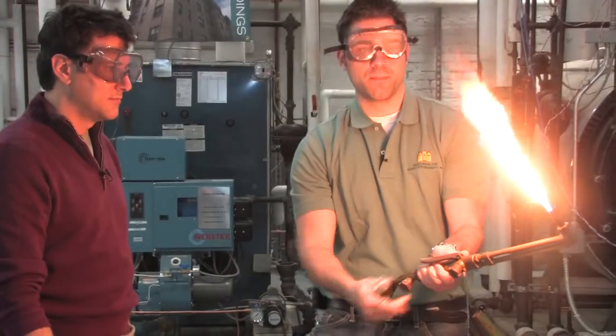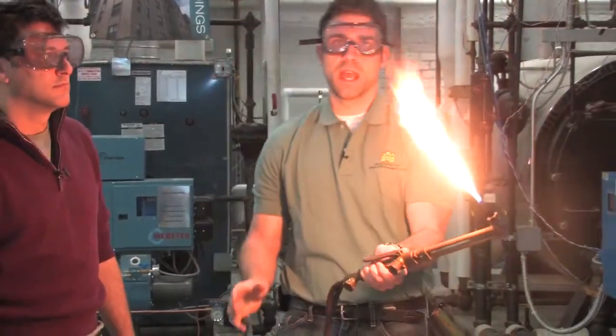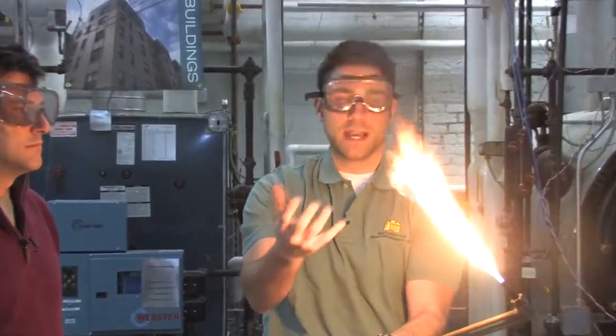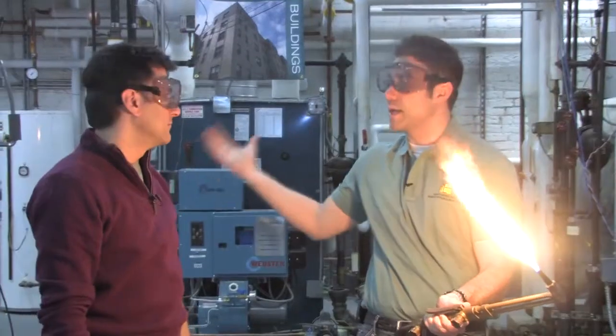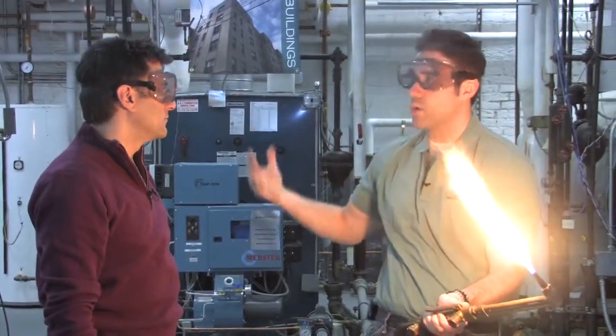So you see the flame. It's a real orange flame. And if you look at the top, you see a lot of the black soot that's forming up here. Yep. Because we're not getting enough ambient oxygen inside this flame to be able to burn completely. And just like in a multifamily building, sometimes on the top, you see that big puff of black smoke. It could be from incomplete combustion that's happening inside a big boiler.